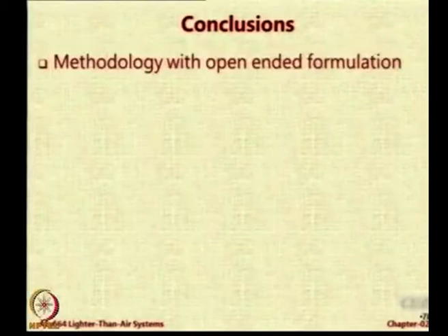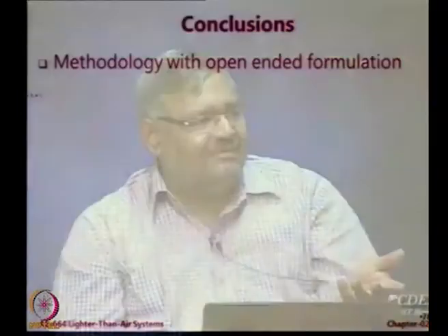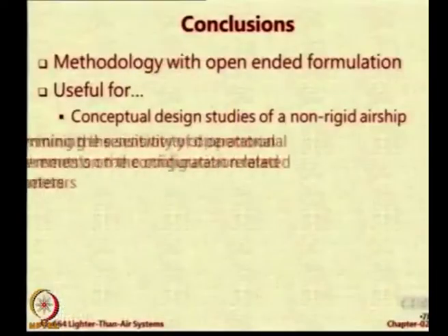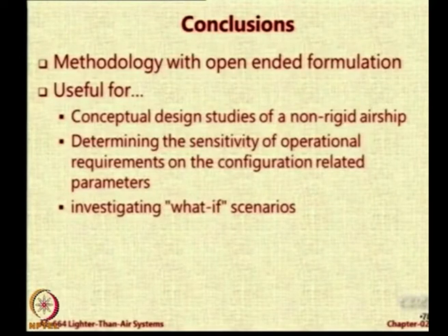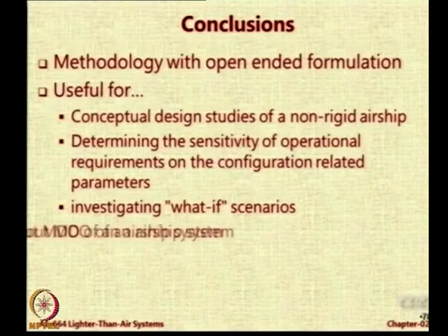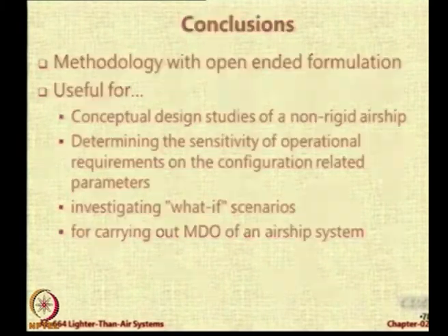So, what is the conclusion? This conclusion is, this is a methodology with open-ended formulation, which means you can modify anything that you feel like in the methodology. It is useful for conceptual design study for non-rigid airships. It is useful for finding the sensitivity of some operating parameters, and it also helps you in looking at what if scenarios. What if the engine changes from petrol to diesel? What if we have a ducted propeller? Okay, and the purpose is to carry out the multidisciplinary analysis and optimization of the airship.